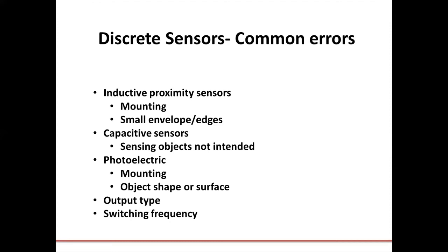Also with some switches like limit switches, you need to be careful about length and type of actuator arm. Sometimes they're liable to have double counts if the object, say, bounces or is light. Let's see, capacitive sensors, they will detect virtually anything. So if any other objects like an arm, a dispensing arm, even something small on the conveyor belt, can be detected as an object. So you need to be careful about that.